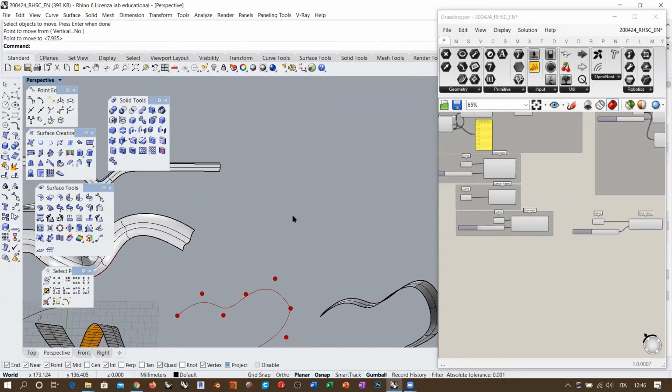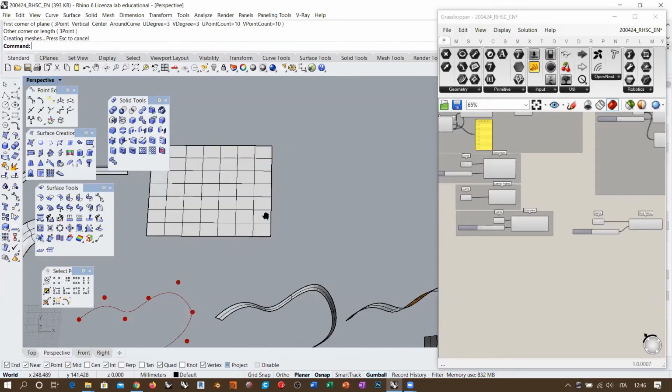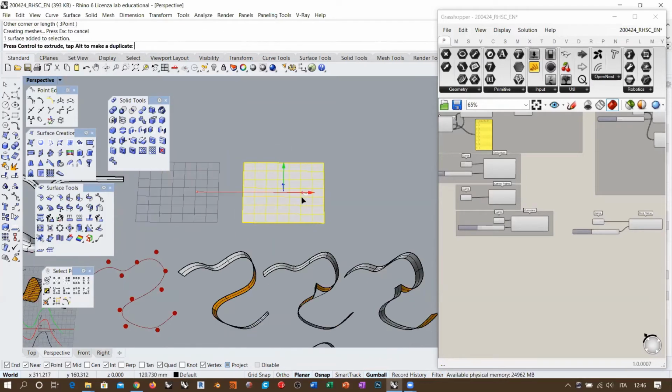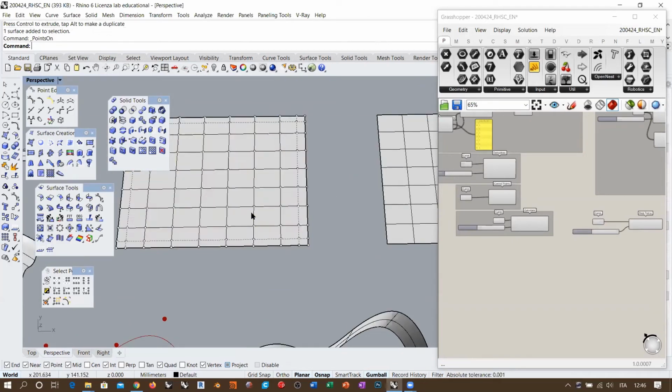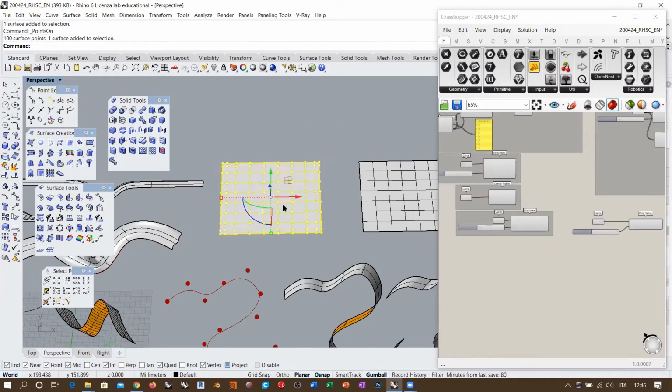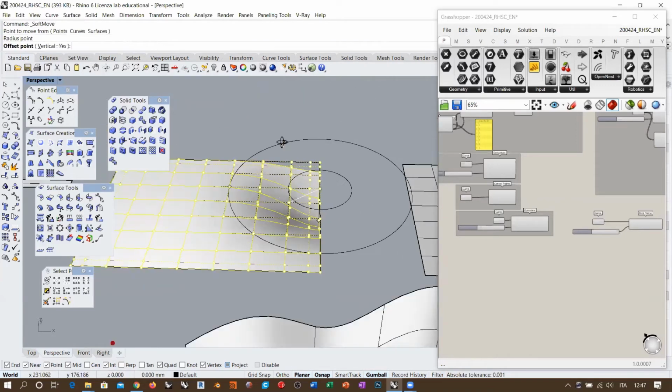creating two double curvature surfaces, okay? So I'm going to create a deformable plane, like here, and I'm going to copy it here on the right. And then I'm going to activate the control points of this, select them all but the surface, and use a soft move command in order to create some curvature, for example, in this area of the surface. Some curvature up,